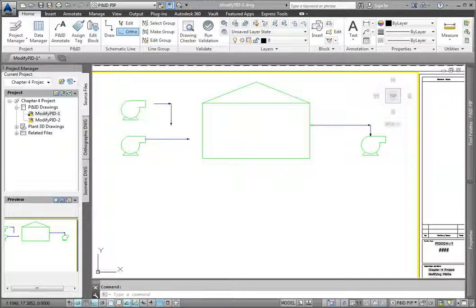Projects in AutoCAD P&ID include a variety of standard symbols based on industry standards. As you start to work on a project, you may want to use different layers, colors, and other settings for the symbols. You may also want to edit the geometry of the symbol. This information is edited using the Project Setup tool, so let's see how we can customize a symbol.